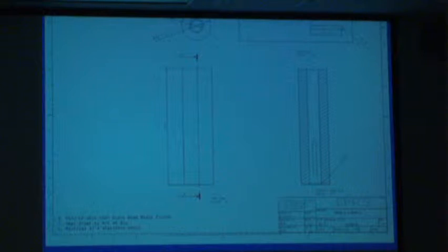So that's key. Down here in the bottom right, you have what's called a title block. This will usually have your company's logo. It'll have the project title, the part number or drawing name, and it'll have who drew the part and who designed the part, so that when there's questions, they know who to contact. Okay. So this is in CATIA. If you're designing a part in CATIA, I can give you this template. If you're designing a part in something else, I can help you get a template. They're usually always built in, and you can just substitute your information. But this is key to making something that is an official print that can be manufactured too.